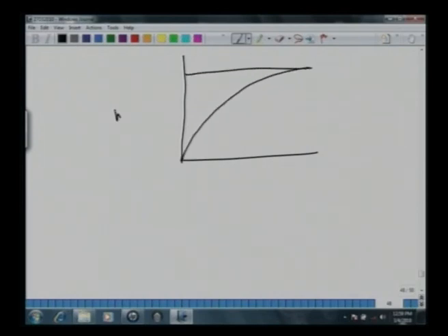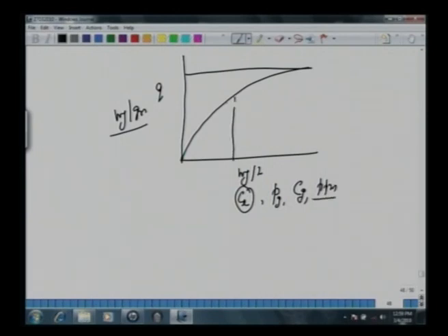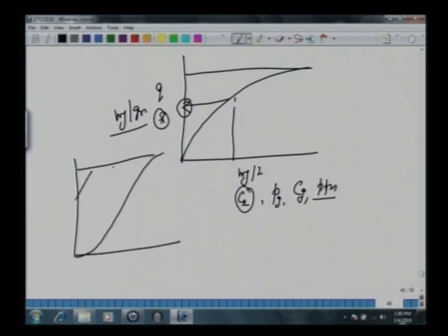So where we plotted milligram per gram, say Langmuir isotherms or BET isotherms or Temkin, Q versus this concentration, milligram per liter, aqueous phase concentrations, or partial pressure of the gas, or concentration in the gas phase, or ppm, mole fraction, etc. If you take this 190 ppm and read this number, this milligram per gram must be the same as what you have calculated just now from this breakthrough analysis, the area above the curve divided by the total amount of this adsorbent. The two numbers must be the same here.